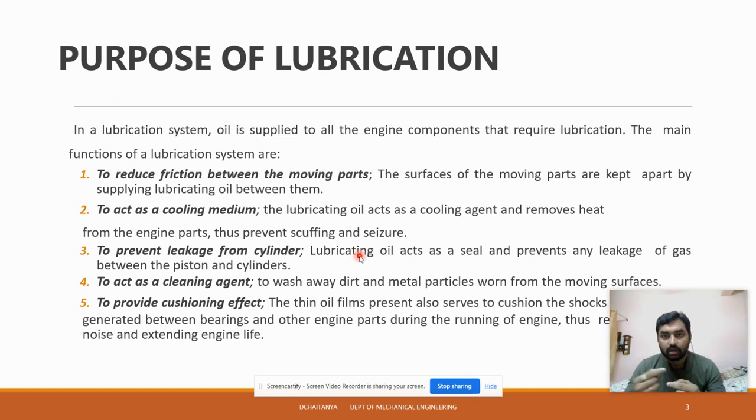But during operation for a long period of time, due to smoke, dirt and waste particles, if you are not having any lubrication, you will observe microparticles in the form of dirt. The surfaces can be worn out, and metallic particles will also be seen during the higher speed movement of the piston, in between piston and cylinder. The lubricant is used as a cleaning agent. Sometimes it also provides a cushioning effect.